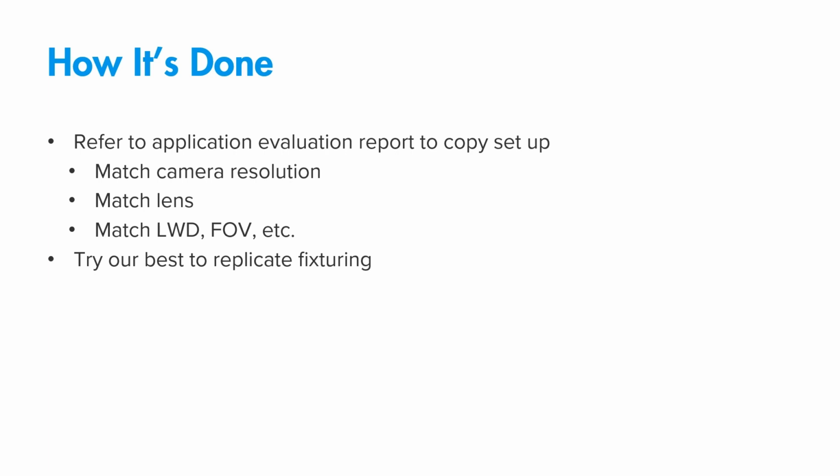But to circle back to how you can use this knowledge in your own lab: if you're doing testing and you find that you're not getting the right image, see if it's possible to modify the setup so that you can solve the application. Change to a color camera, change your resolution, change your light working distance if possible. See if you can modify the restrictions.